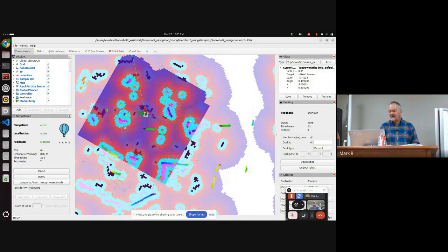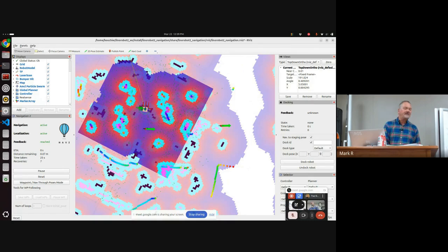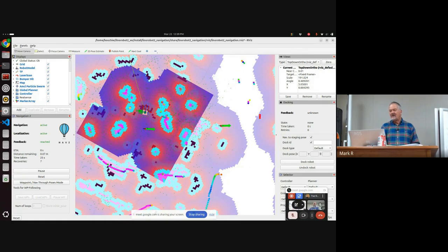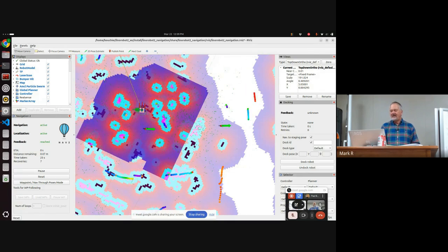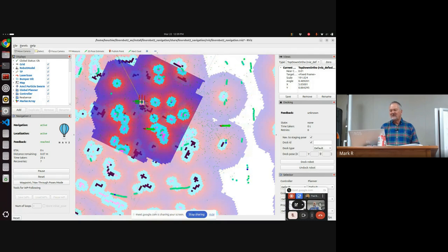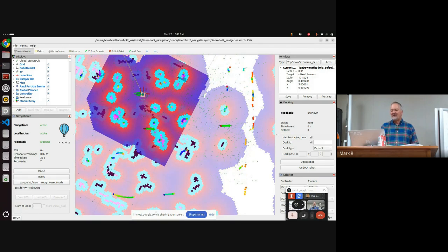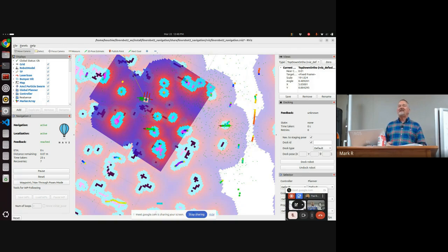So notice that it's moving the cost map along, and the LiDAR obstacles are sliding alongside it. So the key here, okay, it's not in the right place in the map because it just drove over a bunch of obstacles in the map. But the point I'm trying to make is that Navigator is sitting there just monitoring the system, looking for where it is, trying to match up, trying to localize it as it's moving, as something else is moving it through the environment.